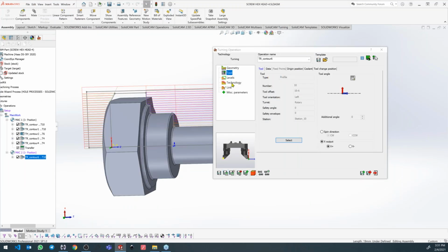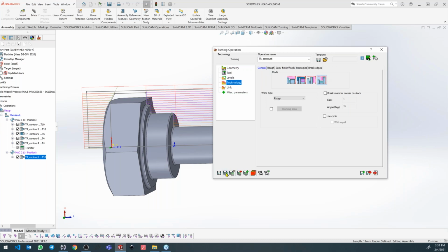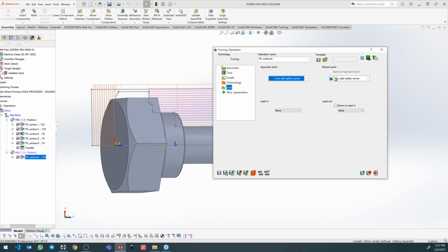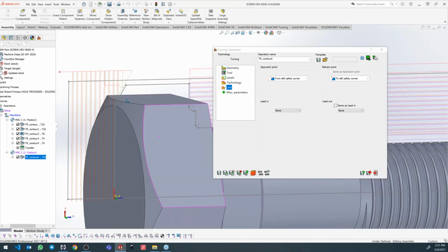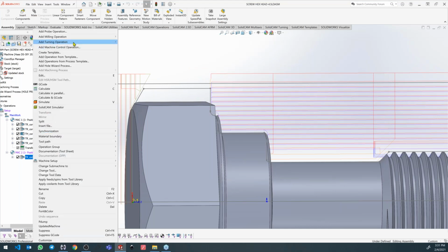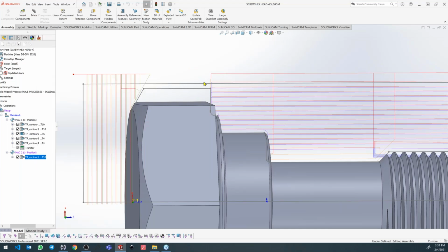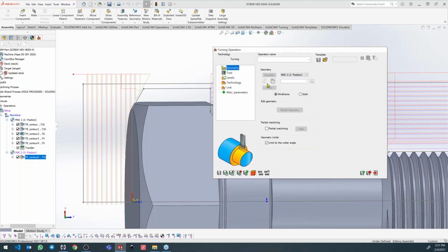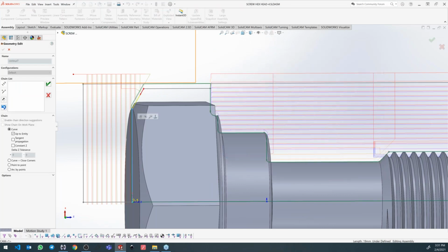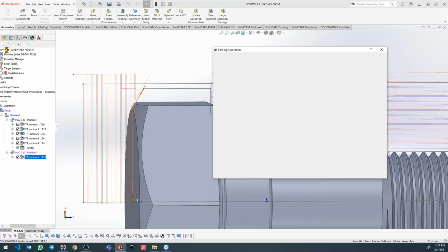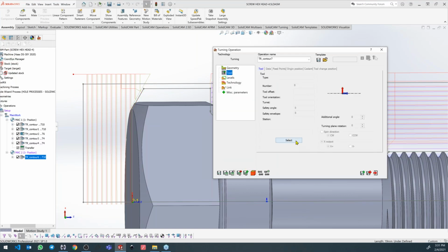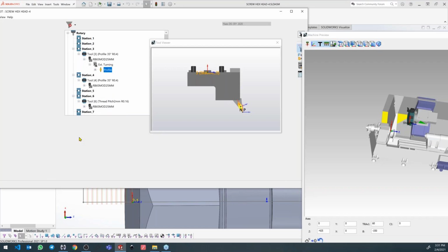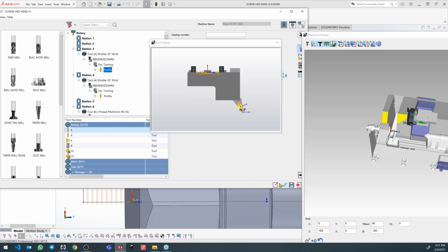I have a tool path here, but of course this tool path will be like a backside spindle. Okay, and I will use it for link the left corner. So here's the rough operation. I'm going to add finish operation and see how we can use same geometry. Select the back spindle finish tool. Okay, this one, number 3.